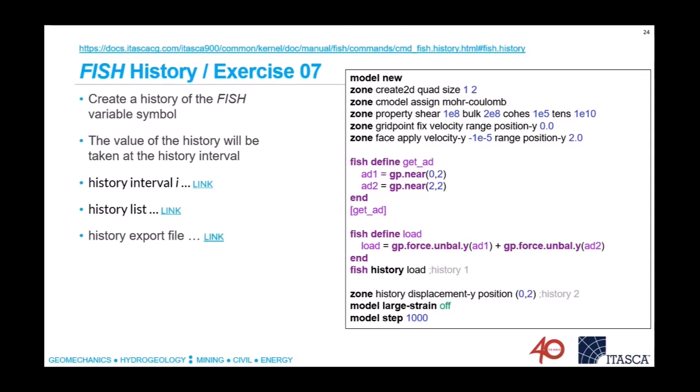And I'm sure they pointed out to you that we don't actually specify units, but we use a consistent coordinate system. So if you want to work with meters or with kilograms per cubic meter, that kind of controls what everything else has to be. Or you prefer to work in megapascals or in PSI or something like that. Although it gets a little crazy with PSI, we've got slugs and snails because they're like mass units. So it's well documented in the manual though, and there's conversion factors. So it's just like converting to a mass and metric.